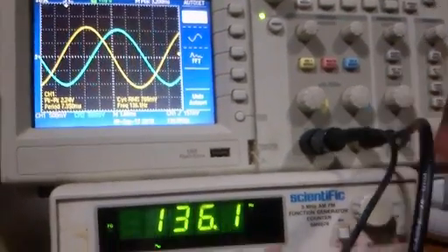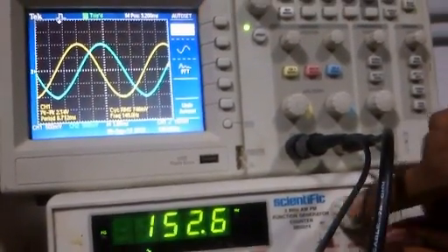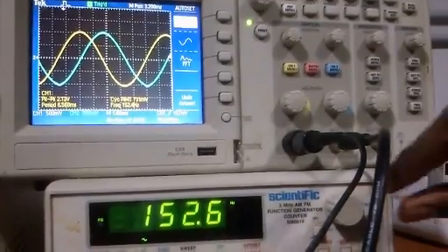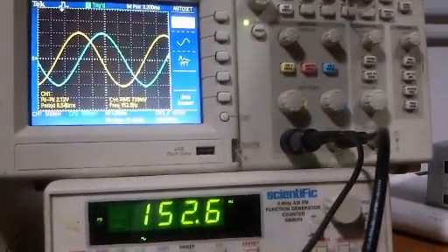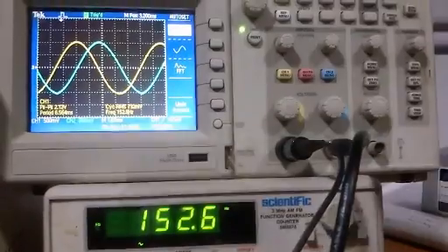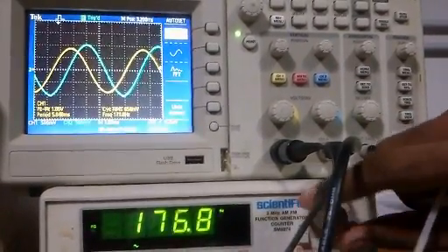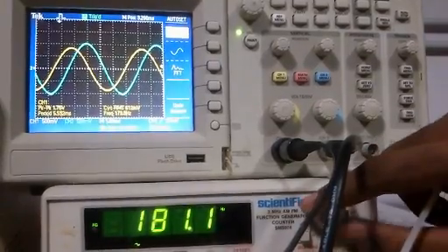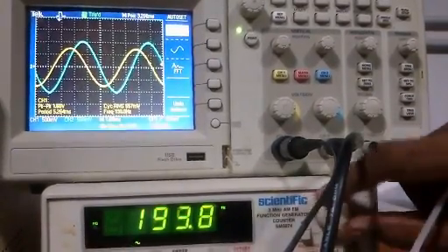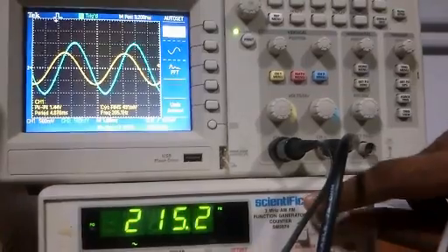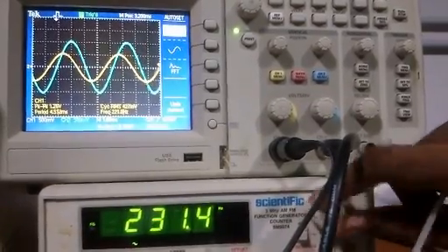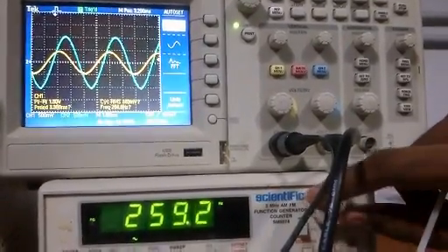And after some time, the yellow waveform starts decreasing in amplitude. So now the low pass response starts kicking in. This is at around 152 Hz. So I keep reducing the frequency. You can see the phase difference is also reducing. Initially the phase difference is 180 degrees, and now the phase difference is closer to 90, and right now it's about 90. So I keep decreasing this,